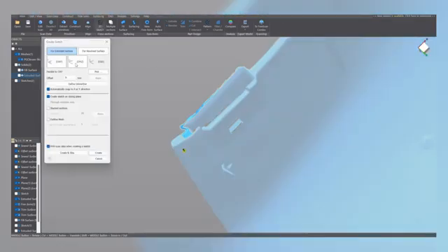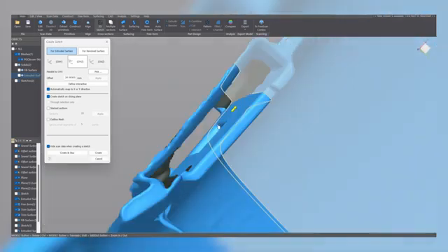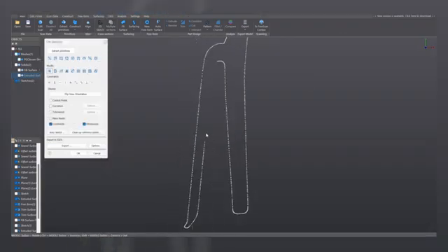To do the cuttings, we repeat the process. We create another sketch, also in this position, so I have enough information. And again, making sure that Create Sketch on Slicing Plane is selected, click on create, and now we focus on the inner walls of this solid.